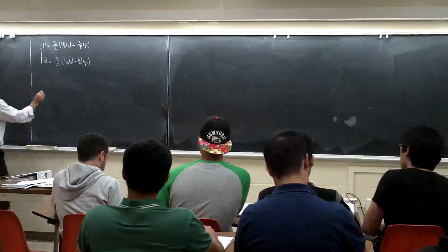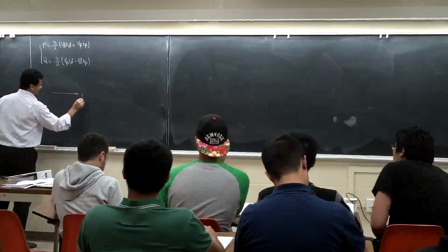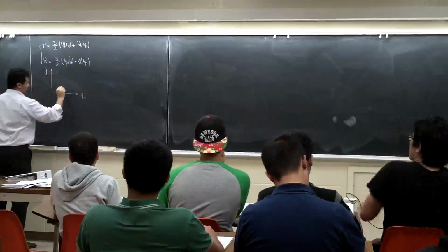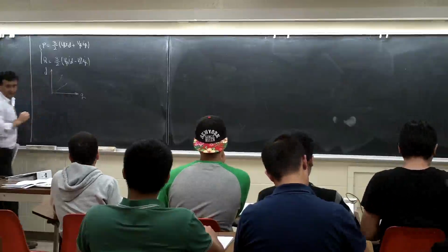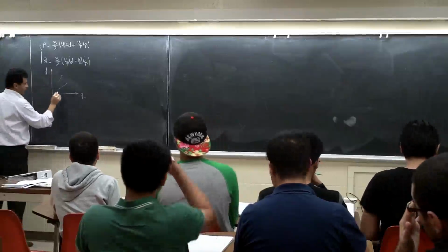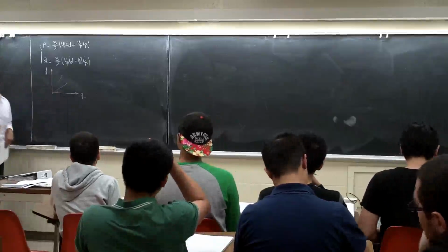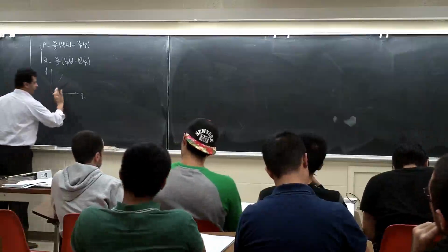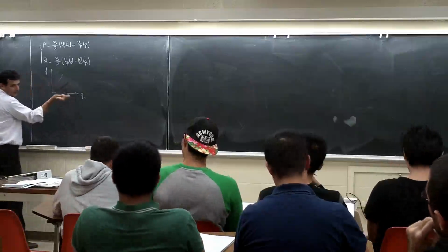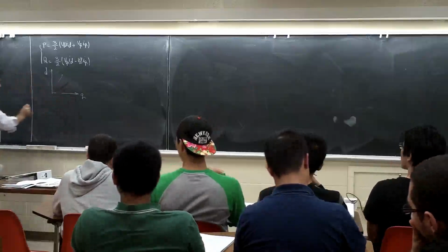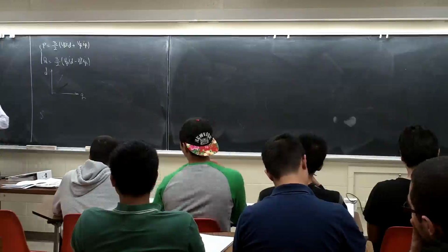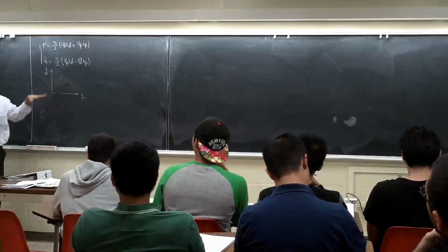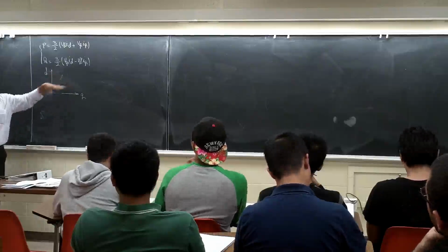We said if we select this as the Q axis and this as the D axis, remember we have a V here and an I here, and we call this one phi V and this one phi I, right? We said if we select this axis arbitrarily, remember there was a delta, the initial angle. I can rotate the Q axis to match my voltage, so they will be in the same axis, in the same direction.